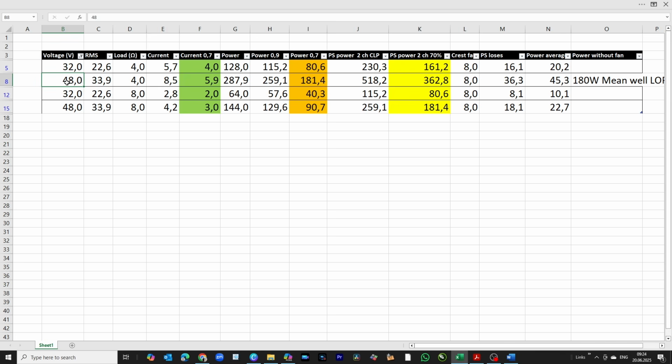And you can see, if we really want a 4 ohm load and full power, we need a 10 amp rated 48 volts power supply. And we can get really excellent power, up to 180, up to 200. And on an 8 ohm load, we can get a nice clean 90 watts. And then we need 48 volts 10 amps for the 4 ohm load, and for an 8 ohm load we need 48 volts, 5 amps.